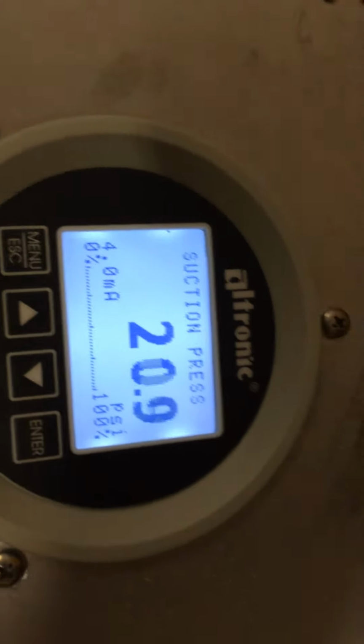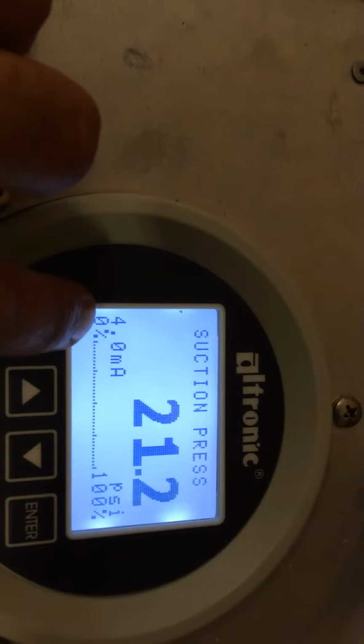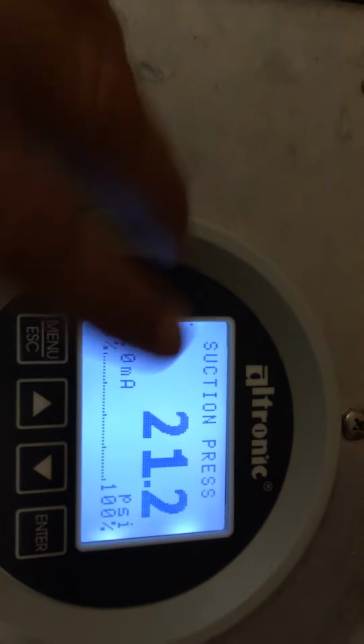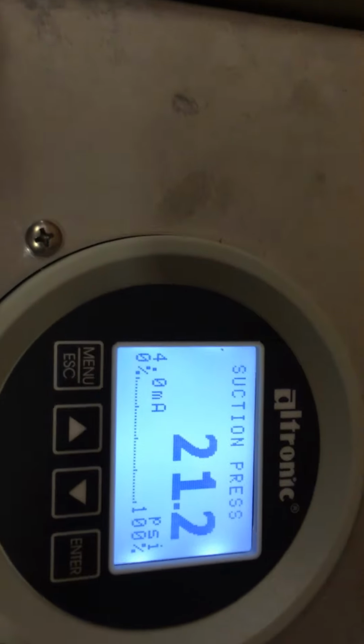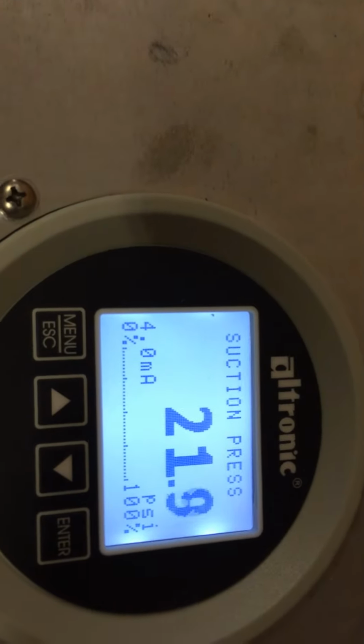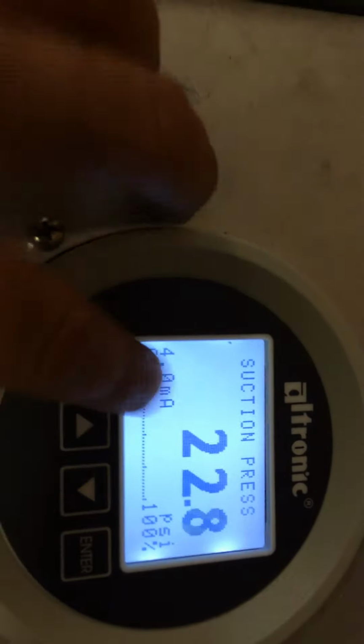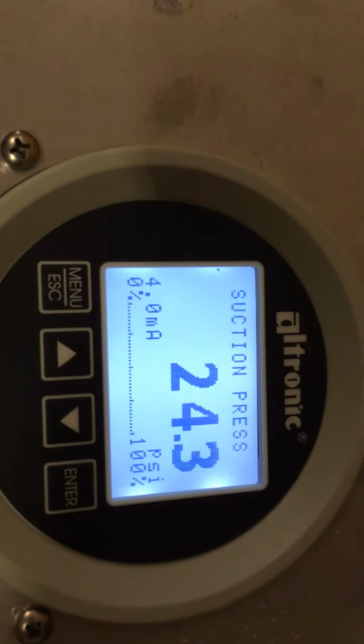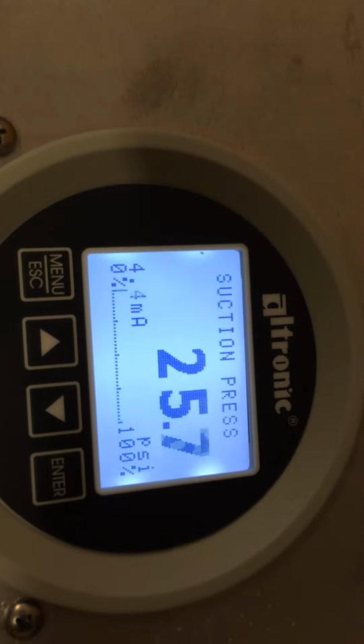So I'm putting out 0%, 4 milliamps. We've offset that value to really not let it go below 4 milliamps because we don't want to go to idle speed. Maybe we've limited it to 1,000 RPM. So that's us saying we're running 1,000 RPM.